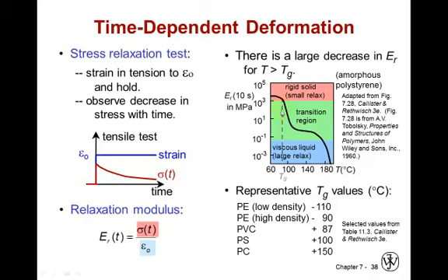Notice how this glass transition temperature is very different for a variety of materials. So this means that at room temperatures, polyethylene, both low density and high density, are actually well within the transition region. PVC, on the other hand, will take almost the boiling of water to make it transition to this much more flexible material. And polystyrene, interestingly, is often processed with boiling water because its glass transition temperature is at the boiling point of water.